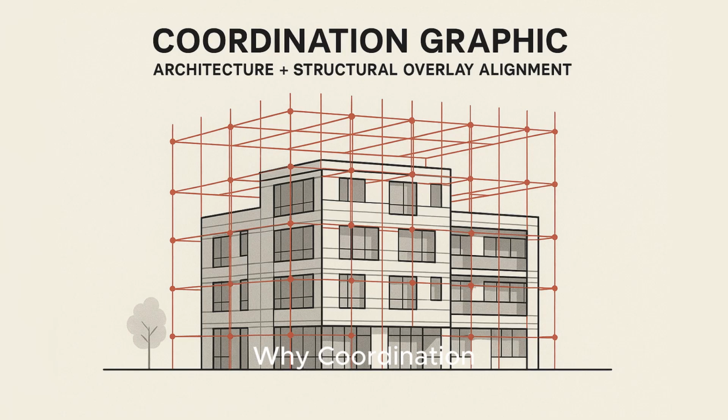Why coordination with the architect matters. Structural engineers must ensure that their design aligns with the architectural layout. Misalignment between beams and windows, insufficient support for long spans, or mismatched floor elevations can cause major redesigns. Good coordination results in efficient designs that save material and time. Structural design fees account for this coordination effort, especially when revisions are required.